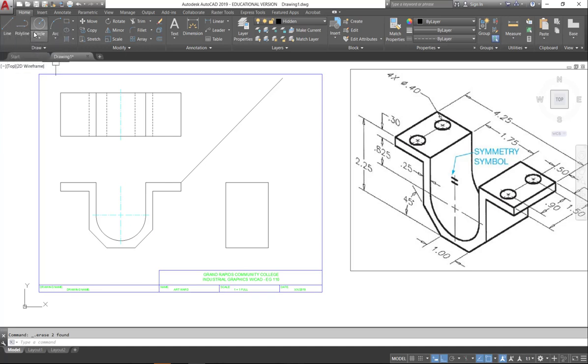So what I'm going to do is I'm just going to offset 0.5. I'm going to use the mirror command this time. And I can see that it's 0.9 between them. So again, I don't want to do any math, so I'm just going to use the midpoint here, and I'm going to offset that. What's half of 0.9? 0.45. So I'm going to offset 0.45.